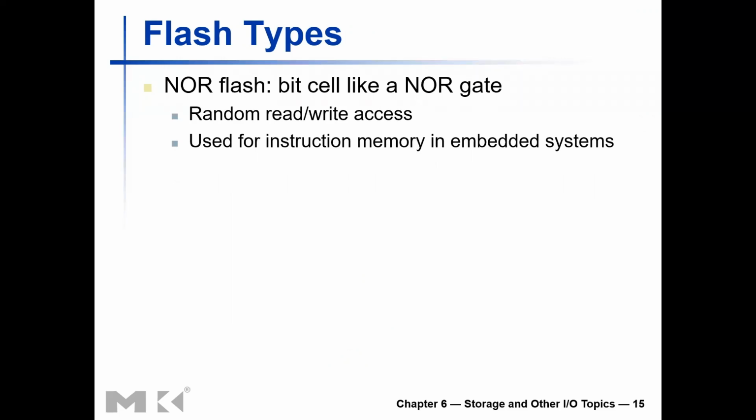NOR flash. The bit cell is like a NOR gate. Random read-write access, so this could be randomly read and written. Used for instruction memory in embedded systems.